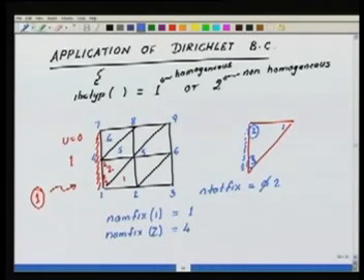Now when I come to element 6, I check whether a degree of freedom which lies on a fixed edge of this element is already accounted for or not. I find that this element 6 again has its second edge on the boundary, and that has global degrees of freedom 4 and 7 as the fixed degrees of freedom. But 4 is already accounted for, so I don't add it again. 7 is a new degree of freedom, so I add it. So now this counter has become 3.